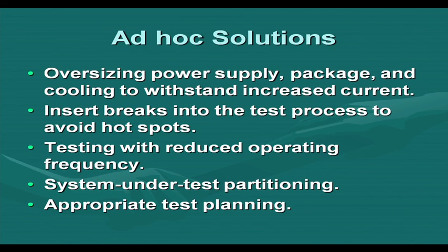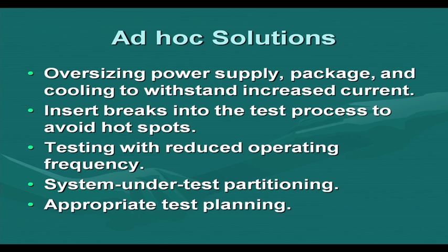And we can also do a partitioning of the system. We can divide the system into different parts, and test the system one part at a time. So, that is another possibility. But again, the thing is how easy it is to partition a system. That depends on the system that we have in our hand. We need to insert some extra multiplexers and other modules, so that this partitioning can be effected. But how easy doing this partitioning is remains a question.